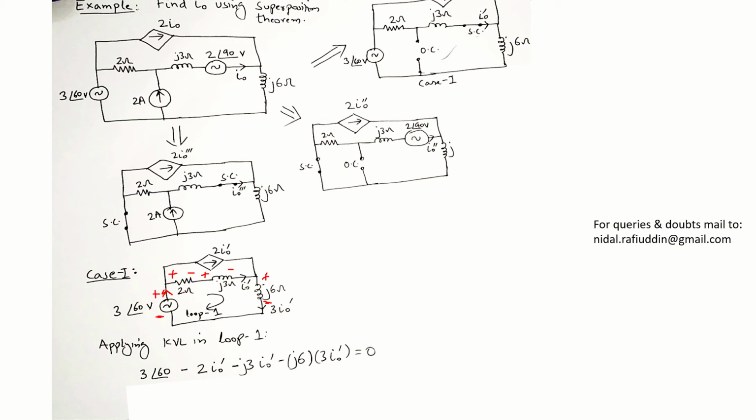In that case, since I have assumed, while writing KVL, that the current comes out from the positive terminal, and probably the current should have been entering the positive terminal, when I solve the circuit, I might get the answer for current as negative. So negative current means that whatever direction I have assumed in the circuit, the direction was assumed opposite to what it was actually flowing.